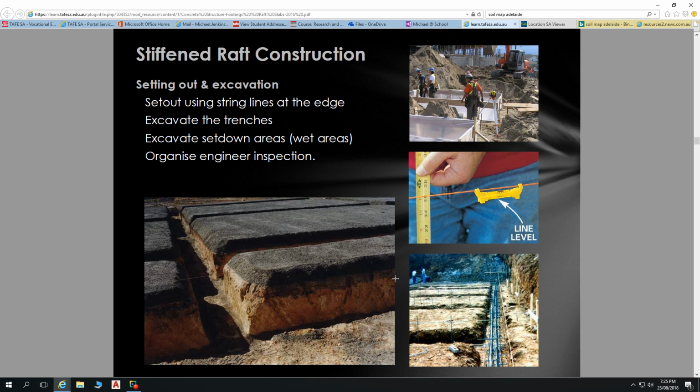And so you pay $300 a cube for your concrete or thereabouts. Although I was talking to a guy who's building a bit more of a crazy sort of place in the hills. He spent $600 a cube on his concrete. So high compressive strength concrete to be able to do certain things. But for your standard N20 grade concrete, so $300 a cube or so.